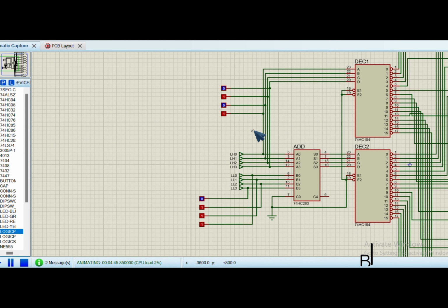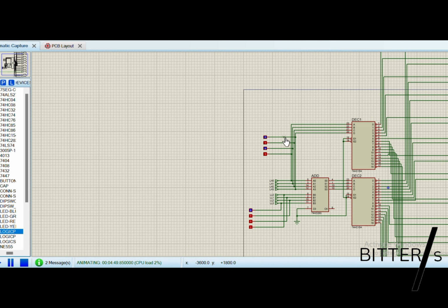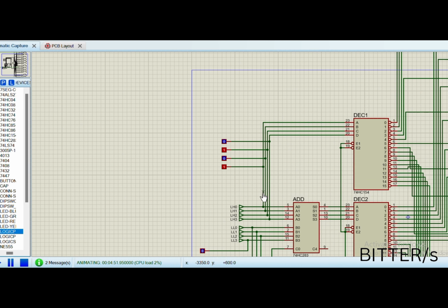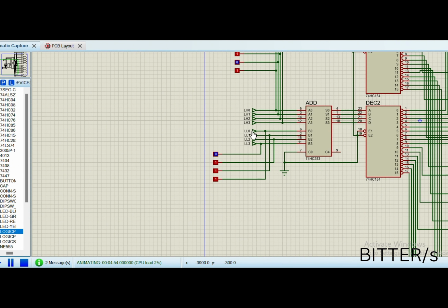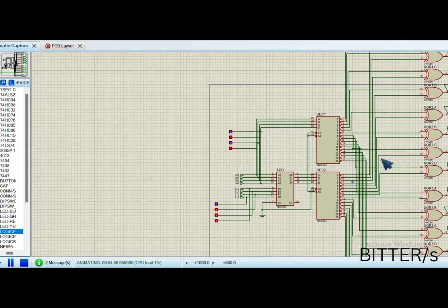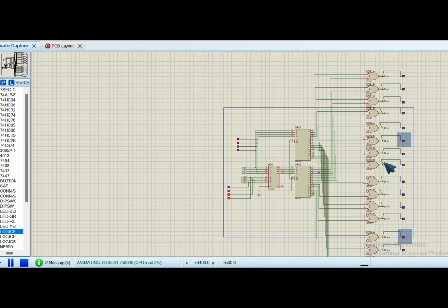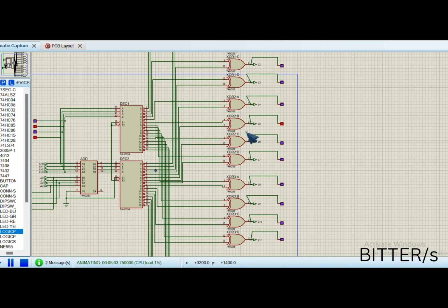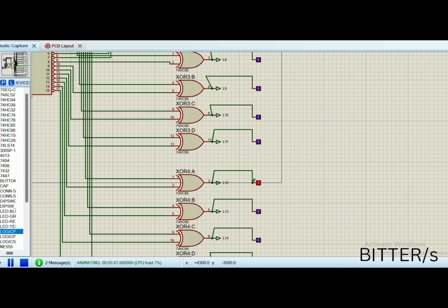we have connected logic probes with the inputs and outputs. So as we set the inputs such that the ladder length is 0111 and ladder head is at 0101, which in decimal is 7 and 5, in the output what we'll be seeing is that, as the board module's spot starts from 0, the 6th logic probe for the 5th block in the board module and the 13th logic probe for the 12th block in the board module will be giving us a logic of 1.